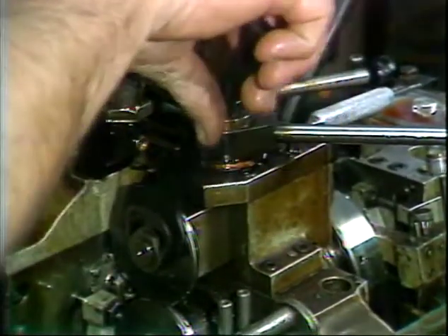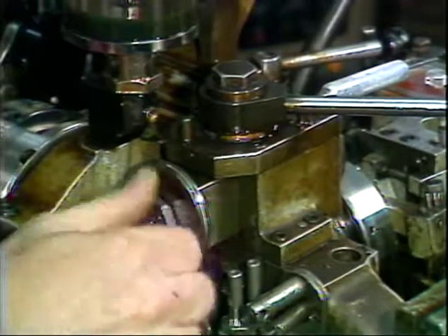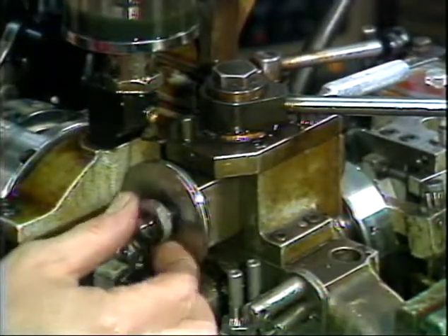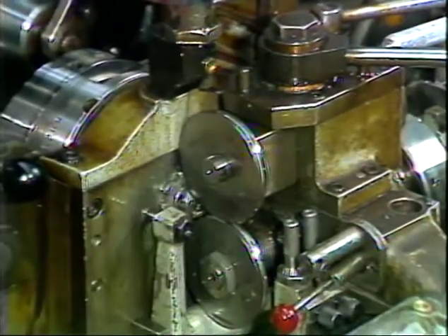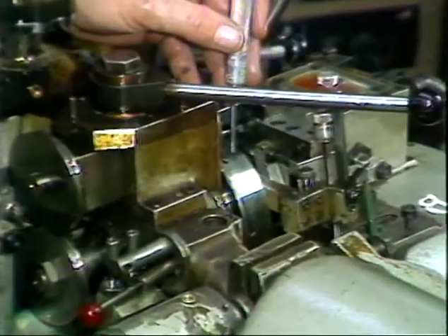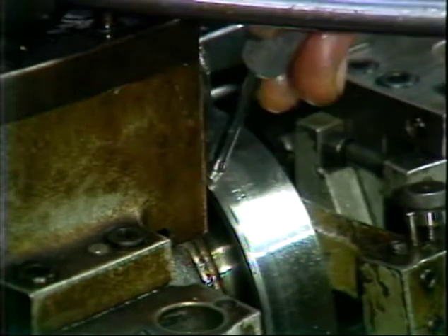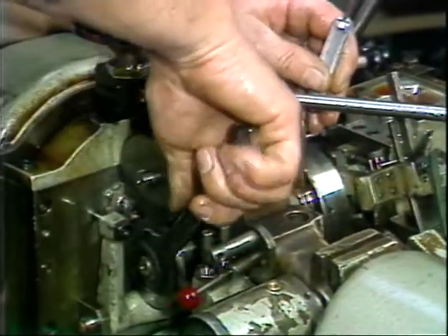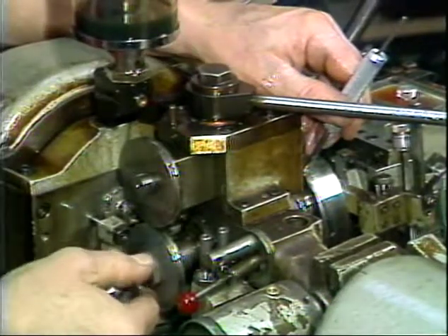With a wrench, loosen the hold-down nut on the feed roll. Remove the nut. Remove the pin from the upper friction disc. Insert the pin into a hole on the friction clutch drum. Hold the friction clutch from rotating while you loosen the lower feed roll hold-down nut. Remove the nut.